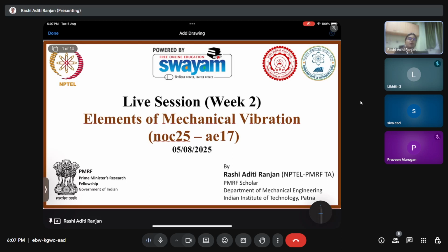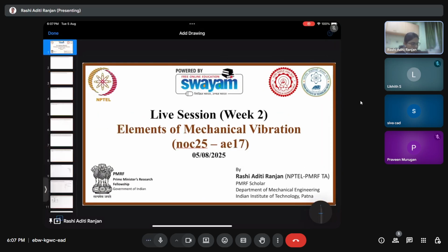Depending upon the equation for a cantilever beam, if we apply a load at the end, then depending upon the displacement, we related it with F equals Kx, and found the value of K, putting in the material parameters like the flexural rigidity, the area, and the area moment of inertia. We used that to find the effective stiffness, and then the natural frequency of the system, right? I hope it was clear to all of you.